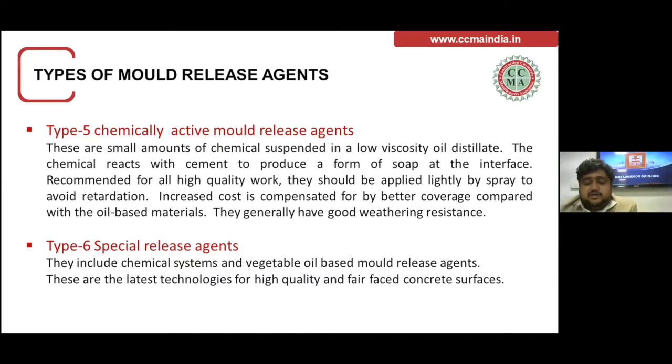They generally have very good weathering properties, so they will not come out very easily, and they are technically very sound mold release agents. I'm going to talk a little bit more about the special release agents in my next slide, because they include chemical systems with vegetable oil based mold release agent. They are the latest technology right now, which gives a very high quality finish at a good price compared to other mold release agents.